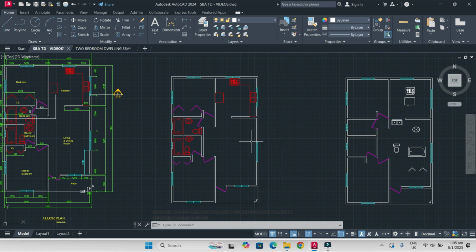So we're going to go into the command text until we say text size. We're going to click on that and we're going to set the value for our text size. So we can use a value of 200. Then now go into text, so T, enter.